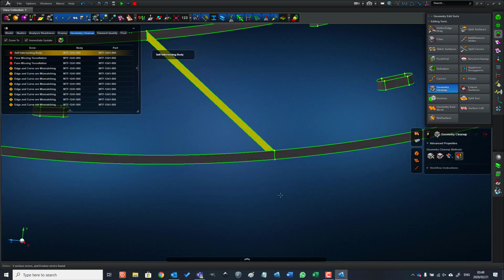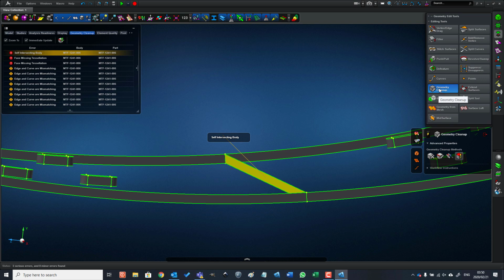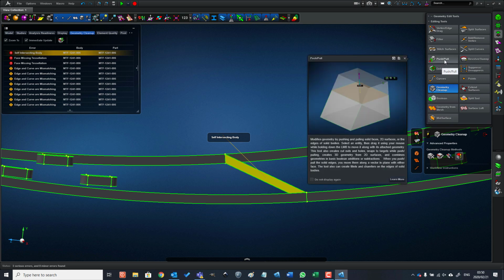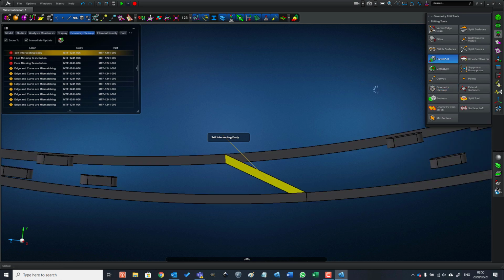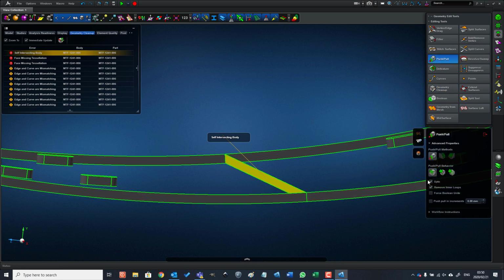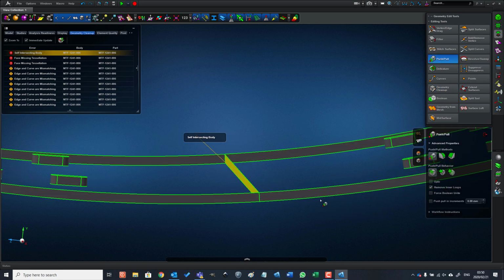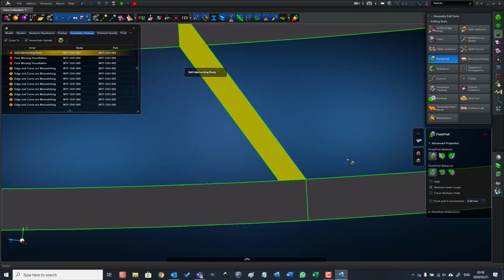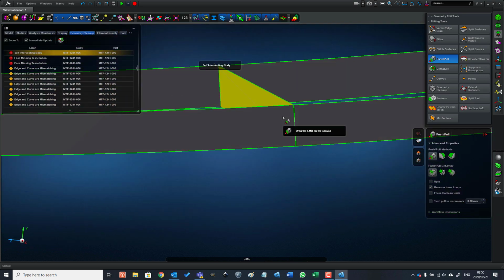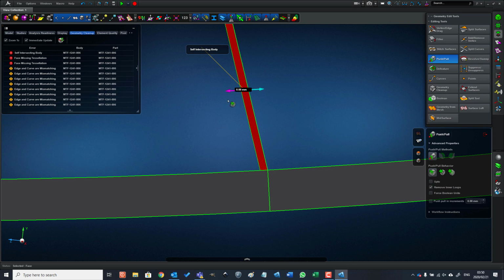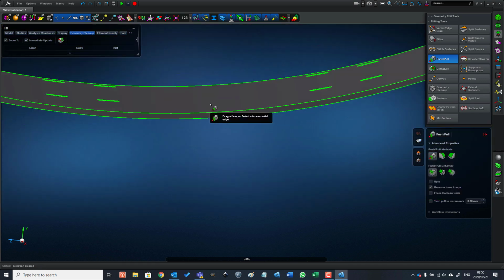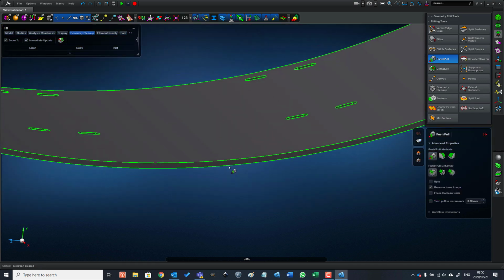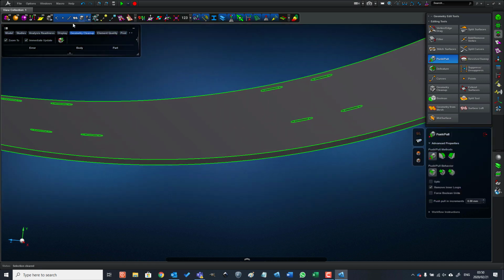Now we can fix this by using our geometry edit tools, and in this case I'll use the push-pull tool. I expect that there are two surfaces in this region and they're not properly connected as they should be. So let's try and pull one of the surfaces in one direction. And we see, yes, that surface has indeed collapsed into the other one and fixed the solid.